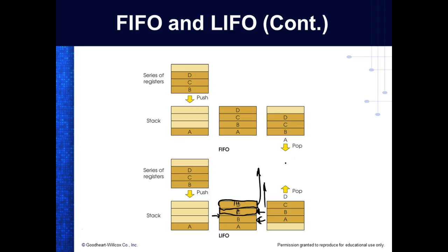But what we do is we can push information on and pull information off with just two instructions, right? You understand? Instead of me specifying an address, I load my stack pointer with where I want it to be at to start off with, and then from then on, I'll leave it alone, and it takes care of itself. It's just that I have to know the order that I put information on there and the information I take it off. The stack is used automatically, guys, when you use a jump subroutine.